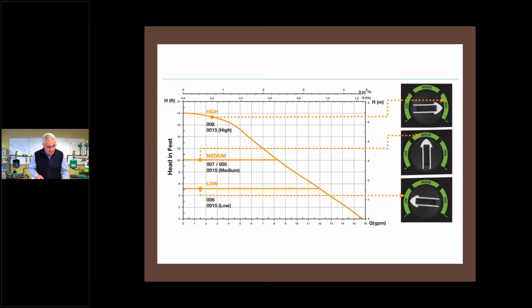We do the same thing for the green zone, 1.5 GPM, also at 6. So it's really the same scenario. Now I'm going to be right at that hash mark here. I need to be at 6 feet of head, so I can either put it at medium, and again, I'll be performing up here, probably overpumping by 1 GPM, squeezing the delta, or I could set it at low. I could set it at low for the majority of the season.